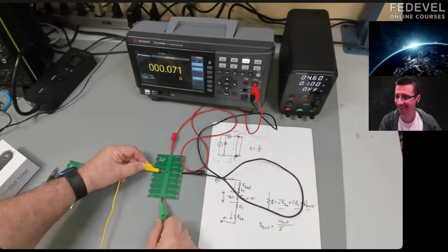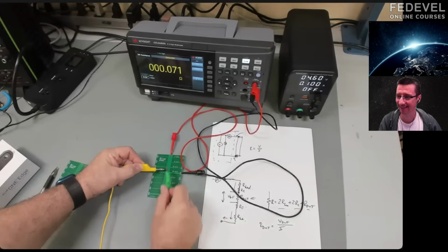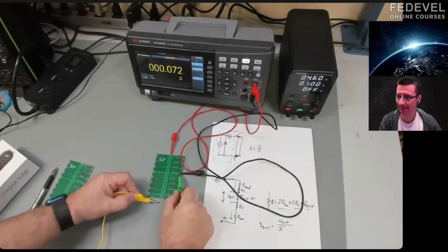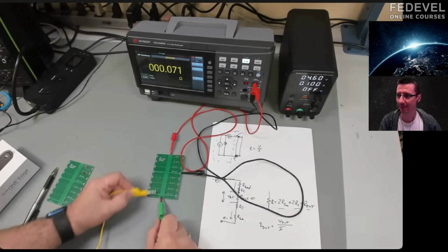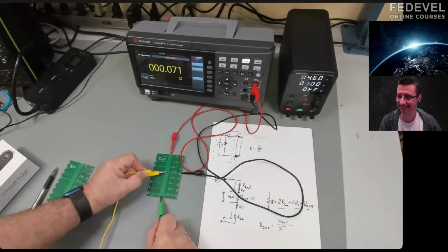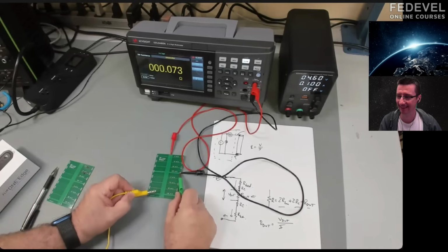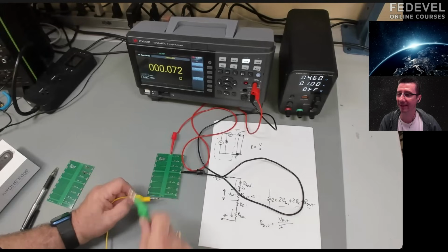It's a trick question, because the only way you get a voltage drop through a resistive element is if there's current flowing through it. If there's no current, there's no voltage drop. So that means that the current's flowing through here to here. There's no current in this path here. That means there's no voltage change. So the voltage I measured down here is exactly the same as the voltage here. And so by forcing current through this path and measuring from here to here, I'm going to be measuring the voltage just across this segment, which is exactly what I want.